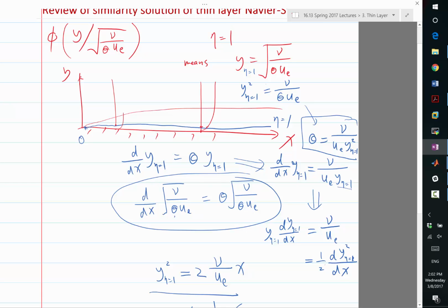And that provides the basis for our coupled boundary layer and inviscid flow solution, which we are going to study after we have a good handle on the boundary layer solutions. So the displacement thickness is a key quantity that goes from the boundary layer solution to the outside flow solution. That's the way the boundary layer and outside are coupled.